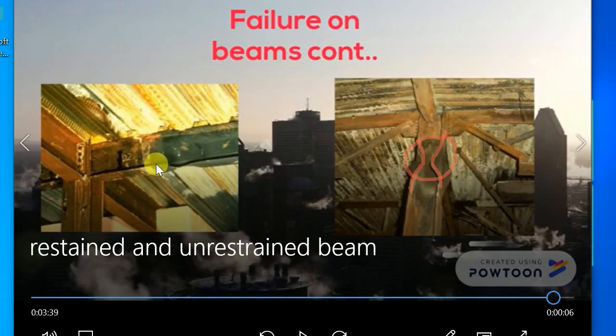You see here the flange is buckled. The web is not buckled. So this is local flange buckling. To prevent this, the section should be compact. Now what is a compact section? We explain this in this example as well. So this is how we can define local torsional buckling and how to prevent it. I will show you more videos. So let us come back to the topic.